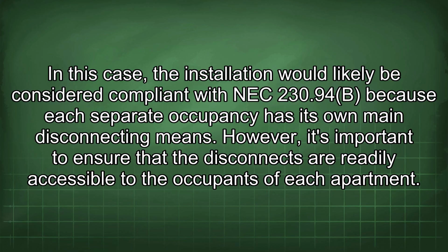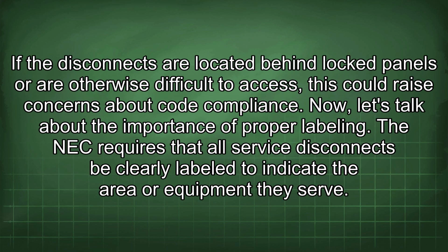However, it's important to ensure that the disconnects are readily accessible to the occupants of each apartment. If the disconnects are located behind locked panels or are otherwise difficult to access, this could raise concerns about code compliance. Now let's talk about the importance of proper labeling.